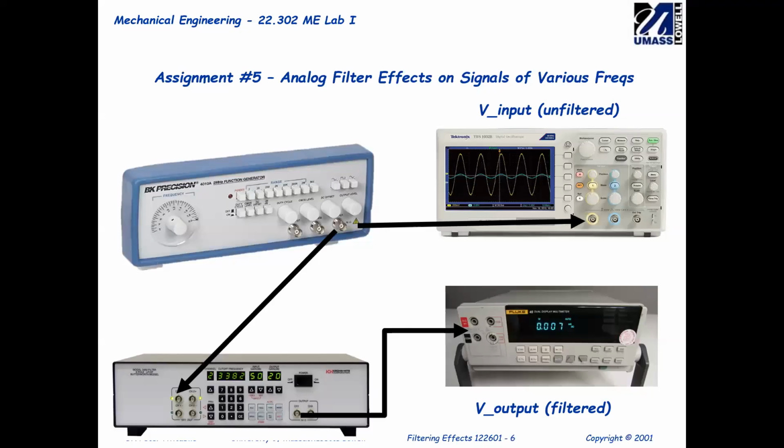Turn on the filter and make sure channel is set to 1. Type in 2000 and press FREQ. The screen under cutoff frequency should read 2, and the freq and kilo button should be lit. Note that 2 kilohertz was set as the cutoff frequency for the filter because it is known from assignment 4 that the 3 dB down point of the multimeter is much higher than 2 kilohertz. This will limit the effects of the roll-off in the measurements caused by the multimeter.